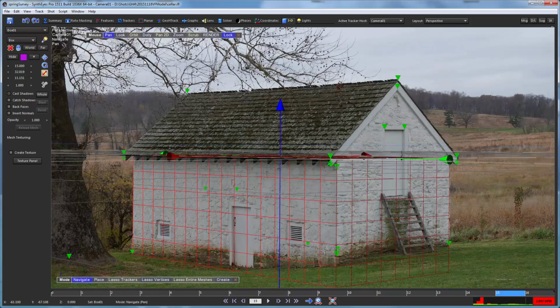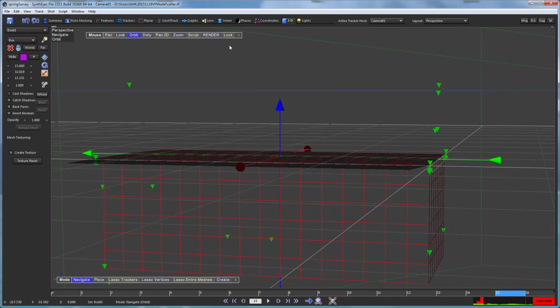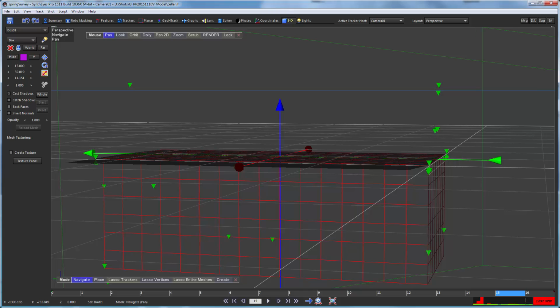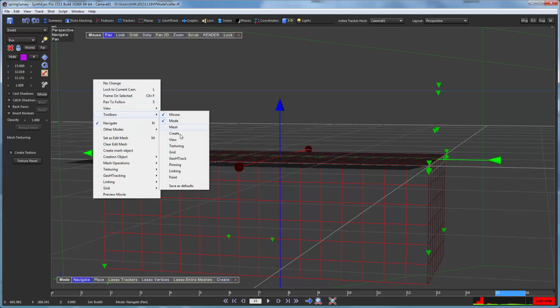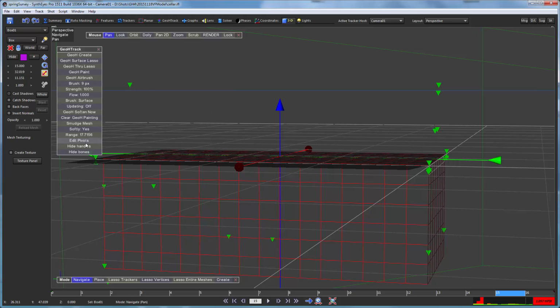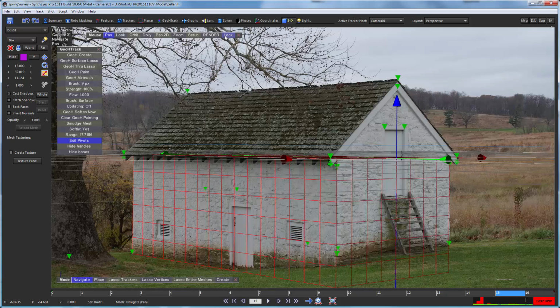One trick that I'll show too here, I'm just doing the orbit, and I'm just going to turn on the geometric hierarchy toolbar to show the edit pivots. So I can go and move the pivot there up to the front of the box, and that's useful.